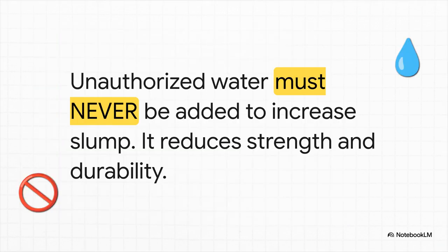I cannot stress this enough. You can never, ever let someone just add water from a hose to a mix that seems a little stiff. It is the fastest way to destroy strength and durability. You are the gatekeeper. You are the last line of defense against this. It is absolutely not negotiable.